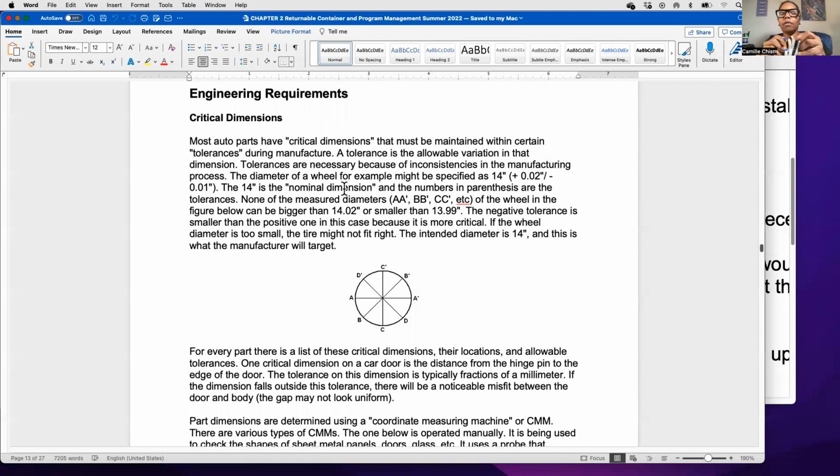But these parts were all 3D printed from the same pattern, and you can see there's definitely a difference based on the material. So it's important to know what those tolerances are, because if you are on the height of the tolerance and you design a pack based on that, the parts may be loose in there. So you kind of have to understand, how do the parts need to fit? What is the tolerance? How much of a gap could there be? And is that going to be a problem? And then building something to accommodate for both of those.